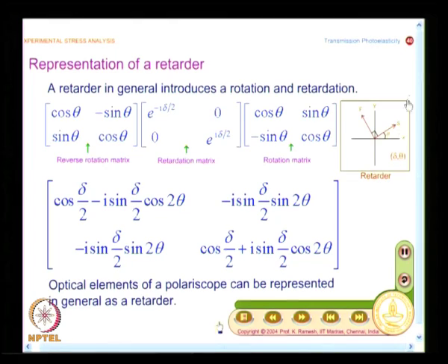You have analyzed it because it is a 2-dimensional model and the thickness is also sufficiently small, and because of the way I apply the stresses, that the principal stress direction remains constant is a reasonable approximation over the thickness. Only then is interpretation possible, because what is the interpretation that we finally come to? We essentially find out what the slow and fast axis are, and this axis should remain constant over the thickness of the specimen. So, the thinner the model, the better, but if we have a thin model, when I apply compression it will buckle.